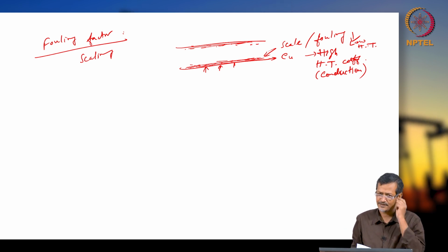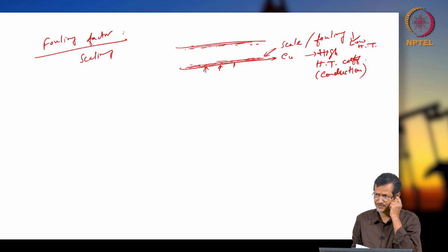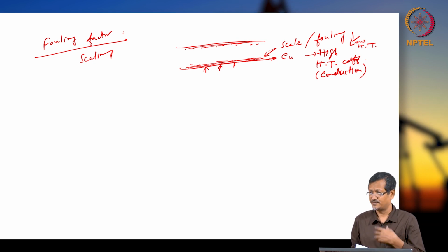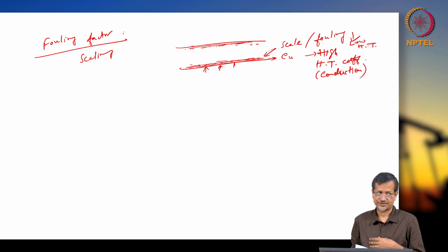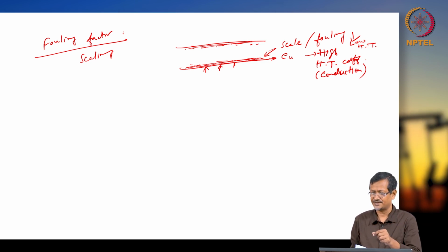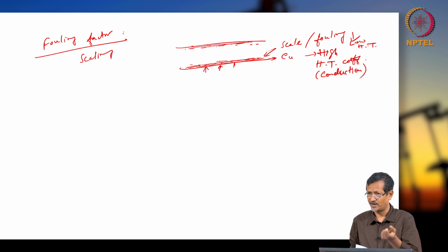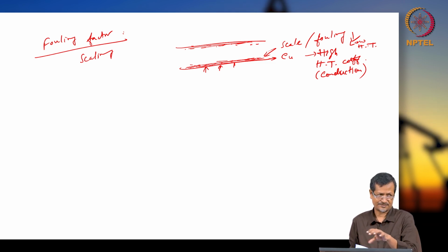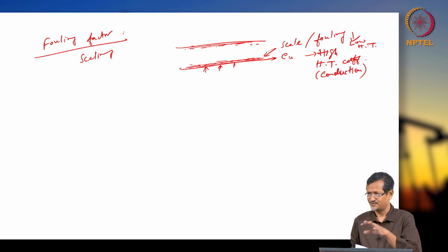Fouling or scaling will be very disastrous in boiler applications, or wherever very high pressure is used. For example, in a steam turbine system, they will be using several hundred bars of pressure. In that case, with very high pressure and fouling, the heat transfer rate will be lower and boiler efficiency will be down. Again, because of this uneven heat conduction, there will be overheating and other issues.